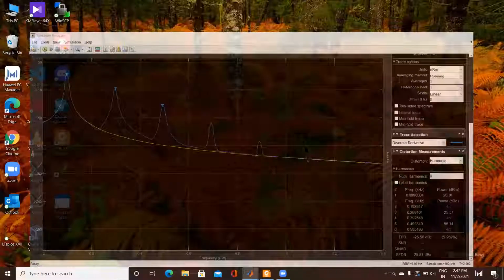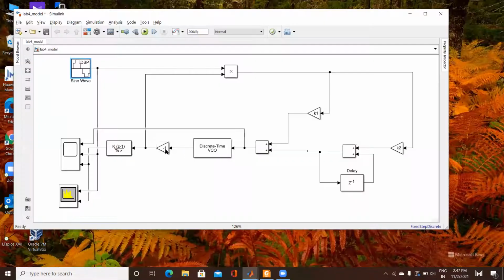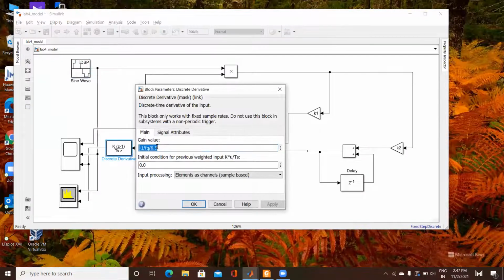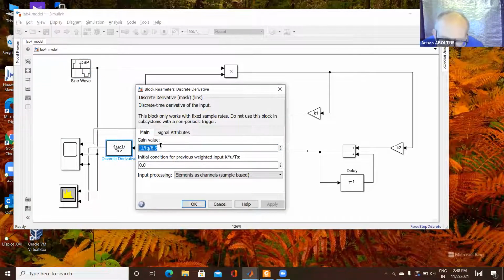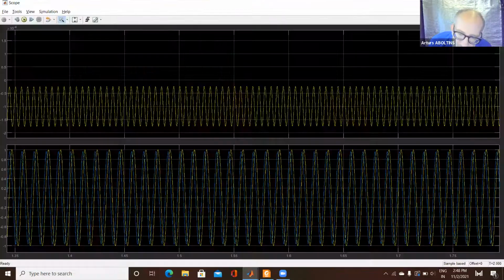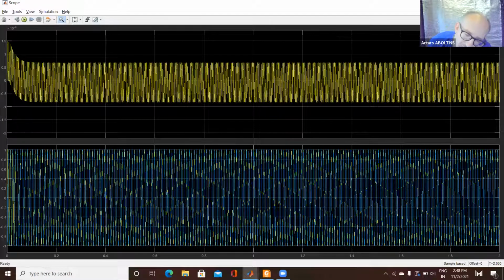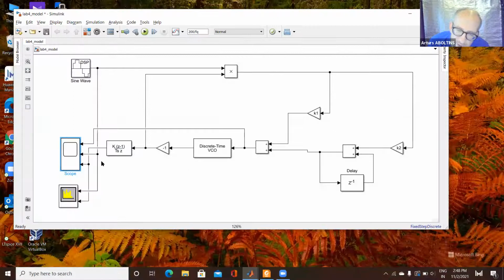Maybe it's because I think you used 6.6. I used 6.3. Yes, this is a problem in reality because this is acting as a filter, and actually the more correct way is to connect directly to this VCO output. But you can try this, because in this case this harmonic distortion will be a little bit smaller if you connect this spectrum analyzer to this -1 block instead of this filter.